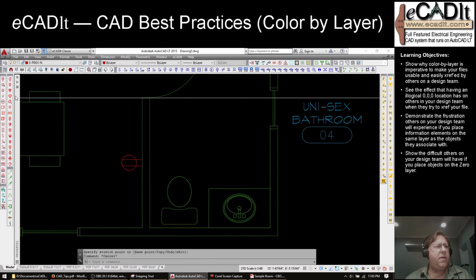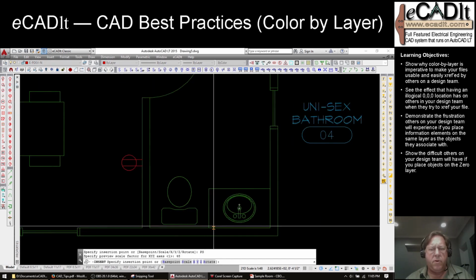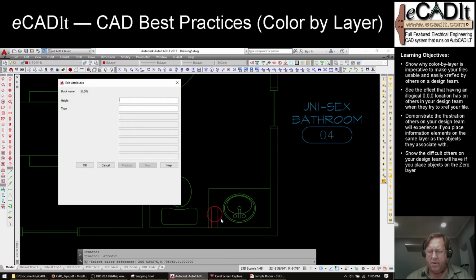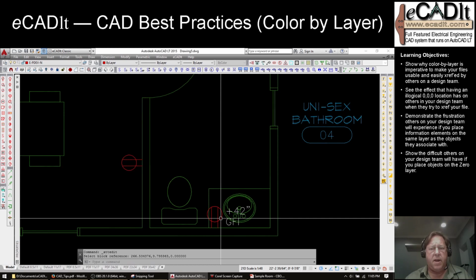Okay, here inside of the restroom, I'm going to put a receptacle to the right of the sink, and we're going to place it about 8 to 10 inches above the countertop. I'd have to check the architectural to find out how high that's going to be. For right now, I'm going to go 42 inches and make it a GFI.